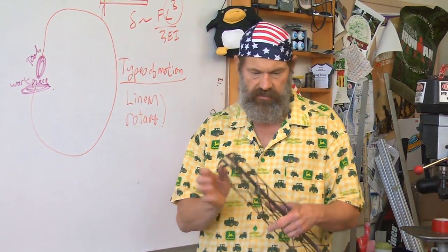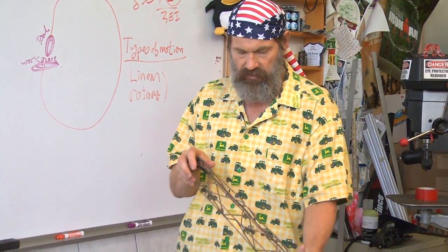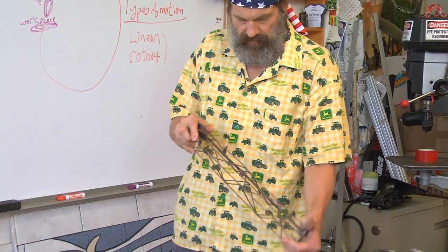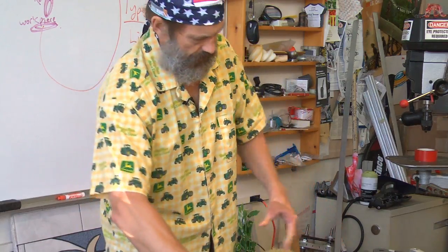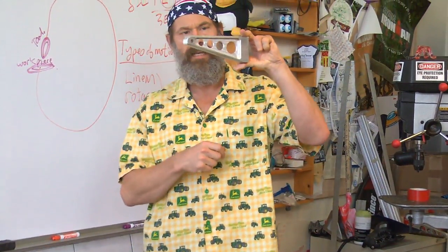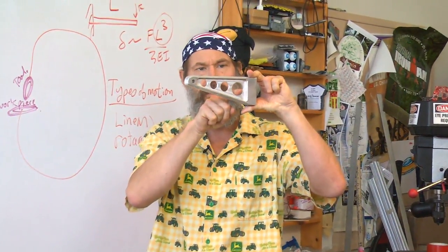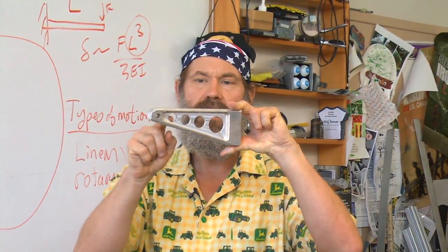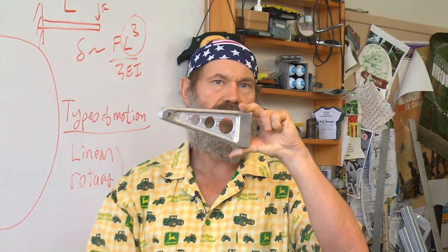Individually, these wires would be very soft, but when you weld them together to form a truss, very stiff. Yet I can actually torque it okay. Why is this beam designed as it is? See, it looks like an I-beam, yet it's tapered. And what do these holes do? Do they just reduce the weight? And is it really worth it to bore out these holes for the weight savings that I get?